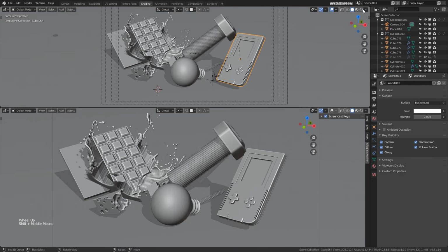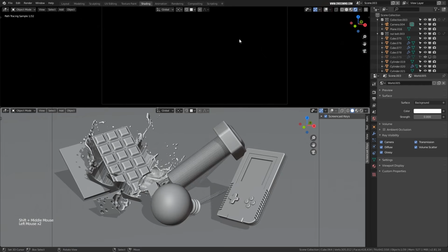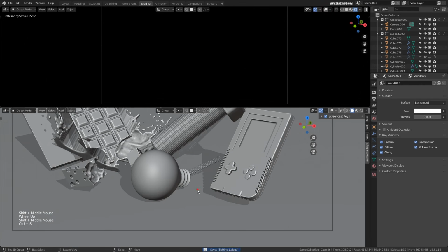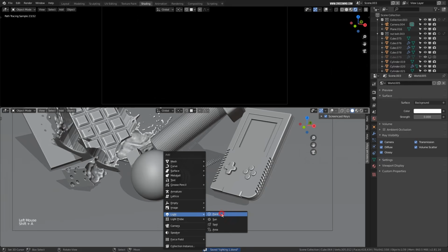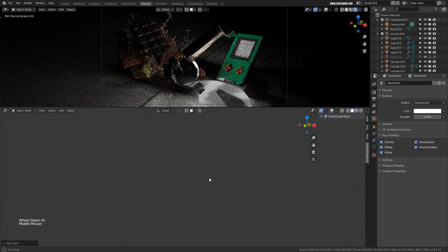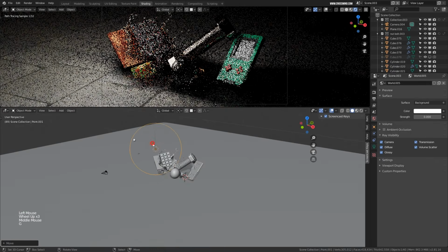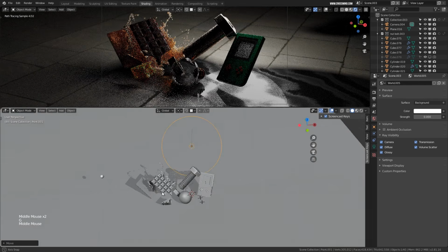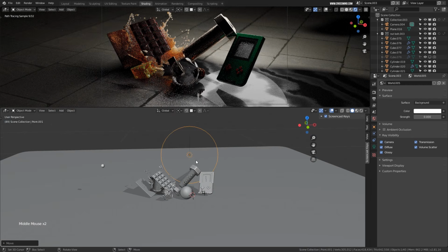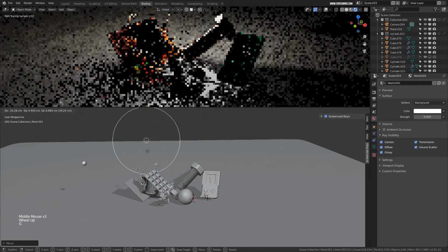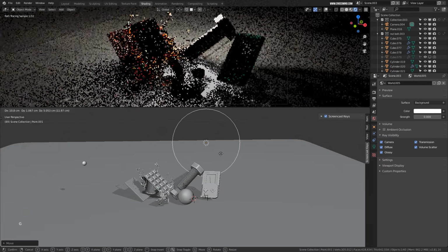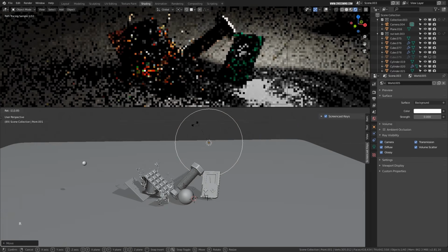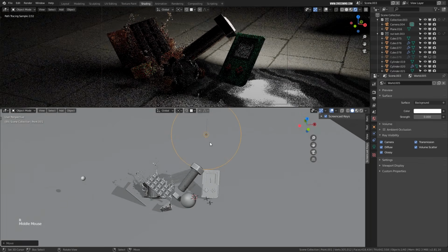I'll go to the 3D viewport and change this one to render. Now I'll click over here and bring in one point light. It's a very simple one-point emission object which casts light from that one point. Since it's a point light, when you change the position it will affect the scene, but rotation won't matter here because it's a one-point object.